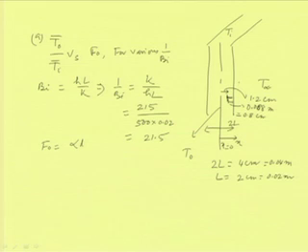And the Fourier number is alpha t by L square. We know alpha is the thermal diffusivity, t is the time and L is the length, and alpha is again k by rho Cp. k is the thermal conductivity, rho is the density, and Cp is the specific heat. If we calculate alpha for aluminum, it is a property of the material.